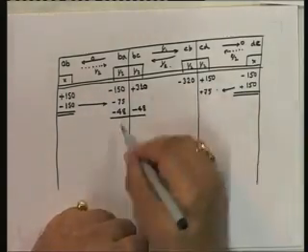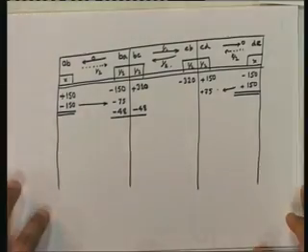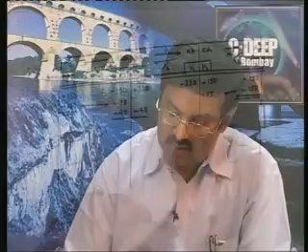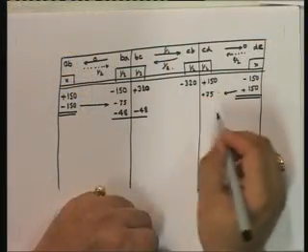Now here this is the point that I was trying to make. I have taken up this problem to show you how we don't do it one after the other. We look at every joint and distribute whatever is the unbalanced moment at that point in one shot. So again here at the same point, I'm not going to be doing the carryover.